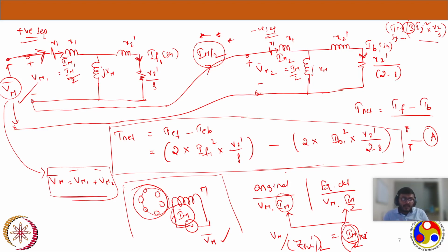So we will see how my exact equivalent circuit expression looks, and we can also verify that the expression actually represents my single phase induction machine. Because in that equivalent circuit, if we substitute the starting condition of the motor, the starting slip is equal to 1.